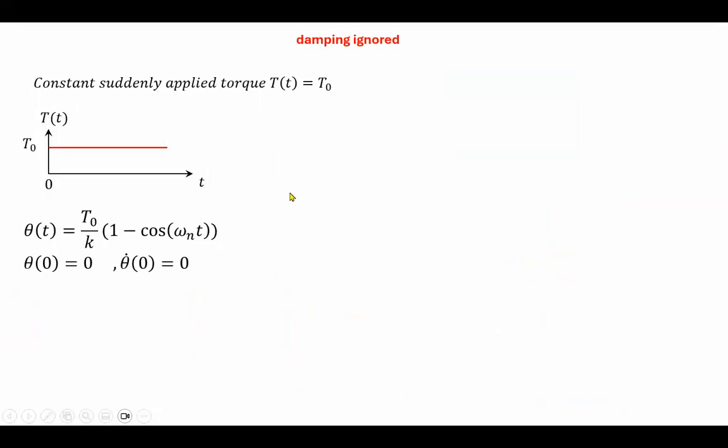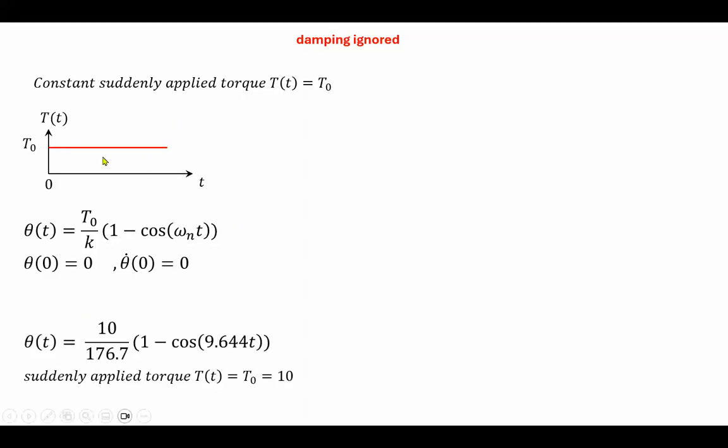Now, we're going to do two problems. First is the constant load. Apply a constant load of T1, with no damping involved in this tutorial. Based on zero initial conditions, one can solve this problem analytically, and you get what you see up here. If you use T of 10 and the K we just calculated, this is what we're going to be comparing with the 3D Experience platform.